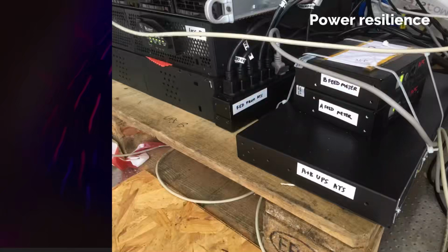Now, the NOC DC was actually positioned where it is because we wanted to use the manhole, or the duct from the manhole, that runs all the way down to the front gate. So unlike previous years, we only had one power feed. In previous years, we've had feeds from 2 different generators, but this time we didn't. But everything worked fine. We had a resilient pair of UPSs and an automatic transfer switch for the servers that couldn't take dual power supplies, and we had no outages at all.